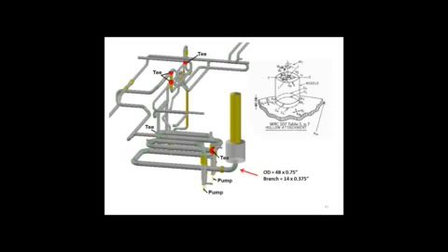This is a rotating equipment model, so the cycles and the stresses aren't so important here. When you see these, the first thing I always do is identify where the pumps are, and then I find where the T's are. And I say, are the T's close to the pumps? So in this system, I see that there's a T that looks like it's close. There's a big head that's not in Appendix D, so I'd need to run another tool in FEA tools to evaluate that elliptical head. And then there's other T's that are removed from the system, but there's a good chance that those aren't going to affect things very much.